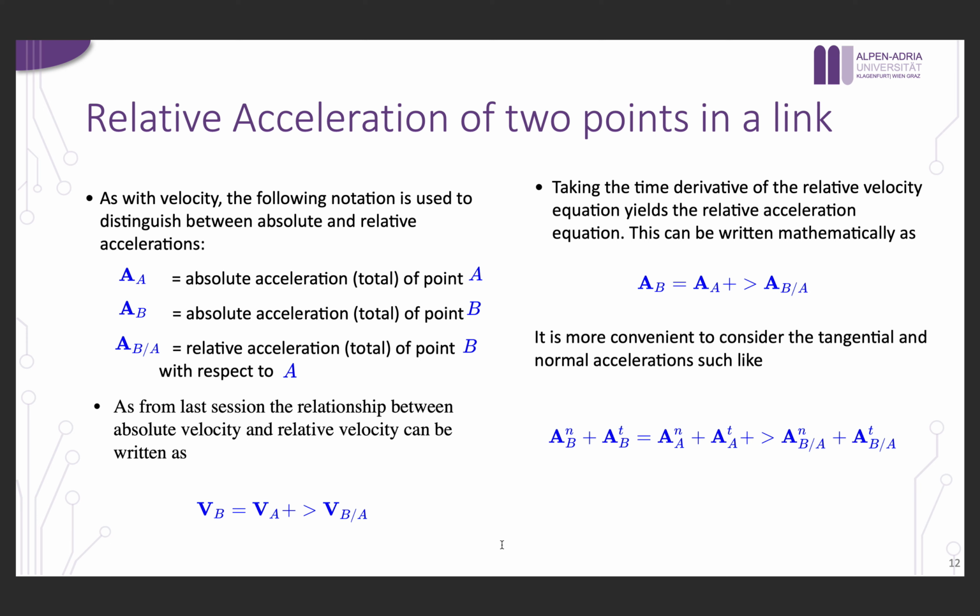So if I had, let's say, two links, and the end of the first link is point A, and the end of the second link is point B, that means A is driven by the motor, which is at the frame, at the base. A has absolute acceleration and velocity in this case, because it is the first moving joint.